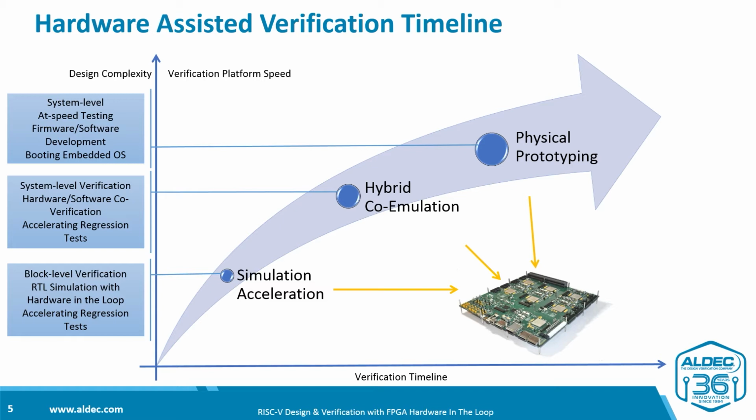The hardware verification team receives a very fast model for running system-level regression tests. And the system integration bugs can be traced conveniently in the simulation-like environment, because the same test benches are used during co-emulation. Now the software team receives a complete and accurate system-on-chip model to run their software and firmware components without compromising any functionality. If the firmware function needs to read a peripheral register, it gets real data instead of fake or stubbed data as in a pure ISS simulation environment.